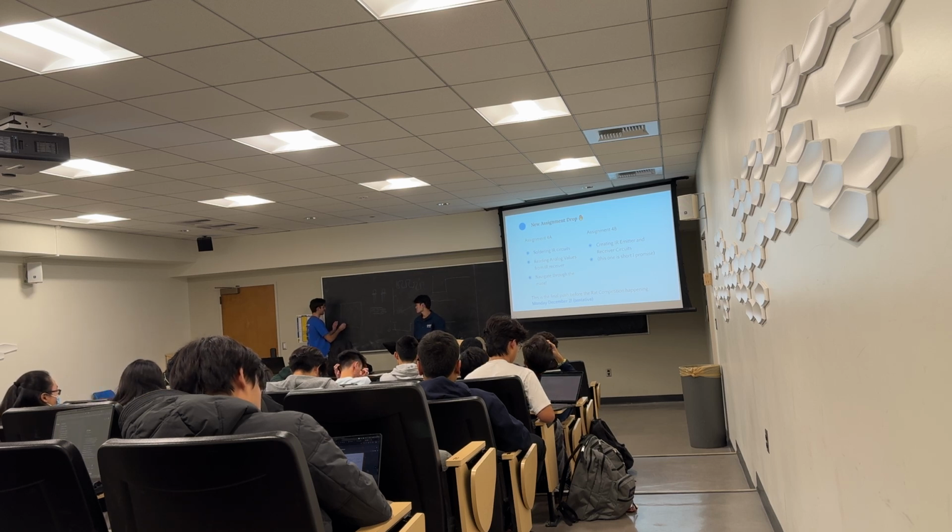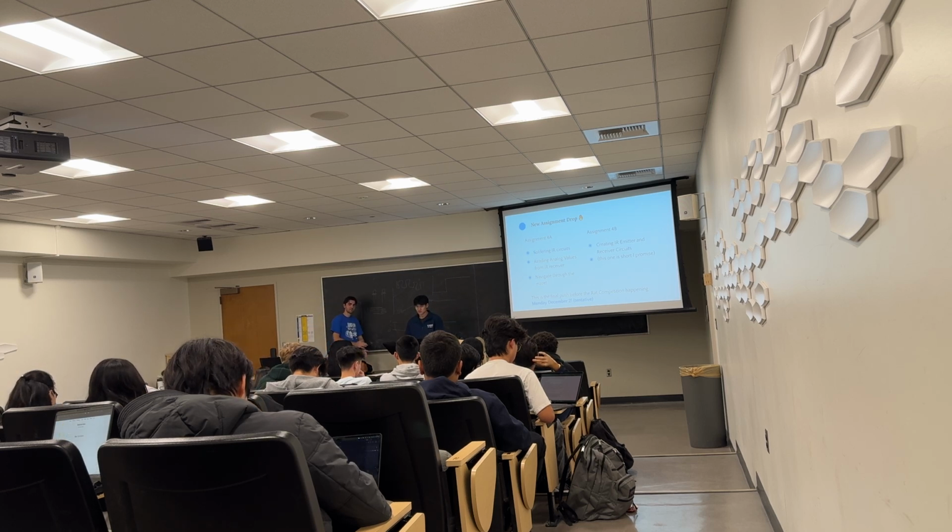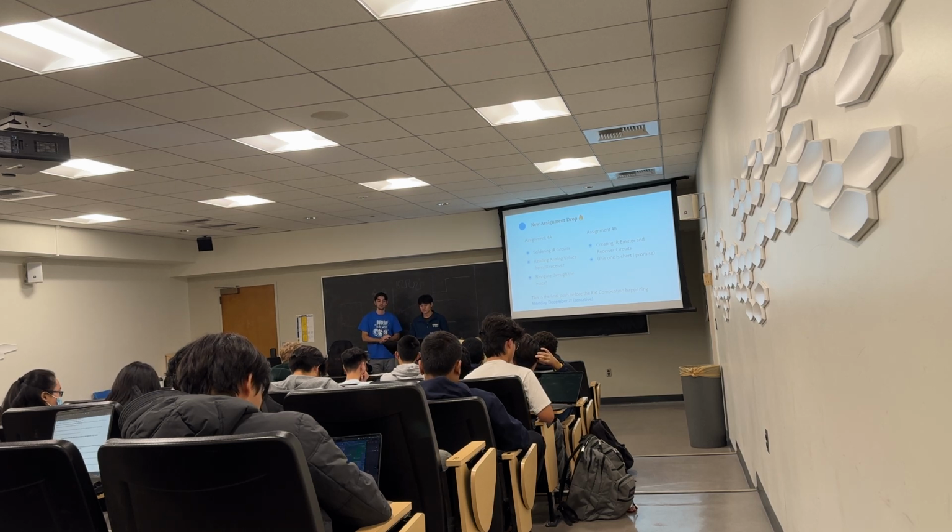So then you're going to construct it. At the start, it's going to say, okay, there's one here, and it's going to move forward one. And it's going to say, okay, there's one here. It's going to move forward one. And it's going to say, oh, there's none here. There's also none here. Okay, move forward one. It'll help you just see every wall in the maze. So many reasons. Also, you can use it to better steer, like if your encoder PID is trash.